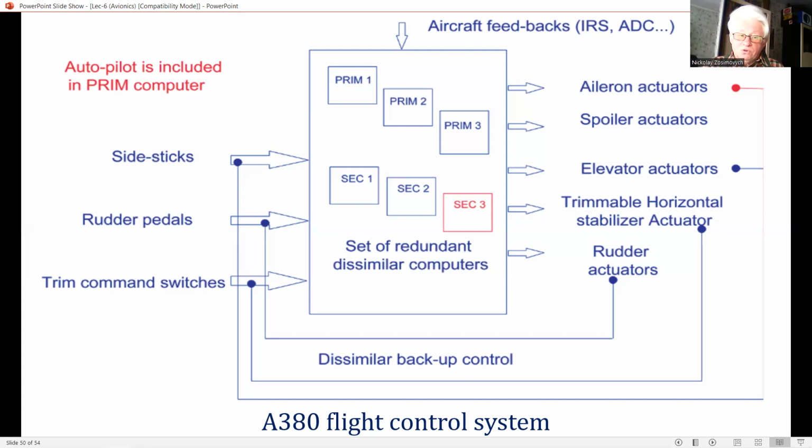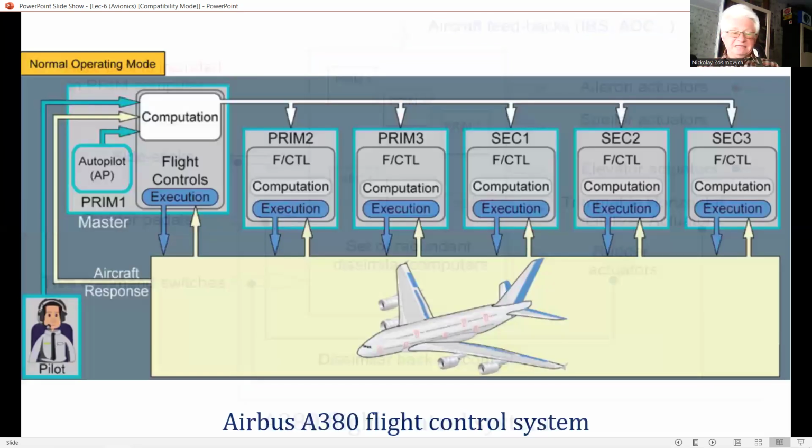Under normal control laws, the pilot exercises a maneuver command control through the side stick of a load factor for the longitudinal control and roll rate for lateral control. Inside the normal flight envelope, the main features are neutral static stability and short-term attitude stability, automatic longitudinal trimming, lateral attitude hold, automatic elevating turn, Dutch roll damping, and turn coordination.